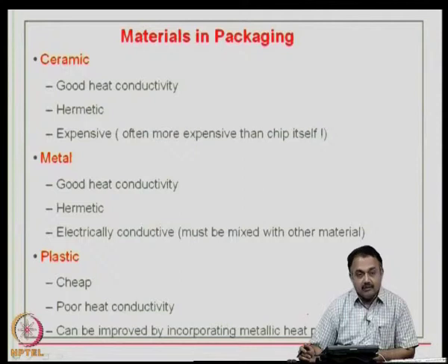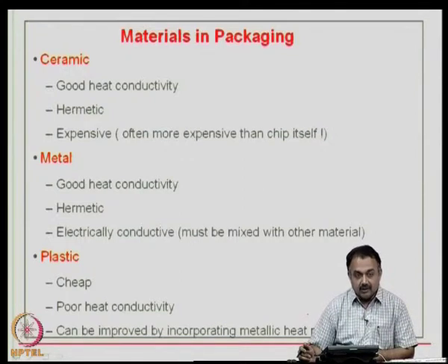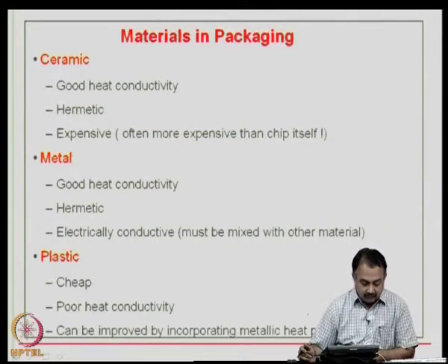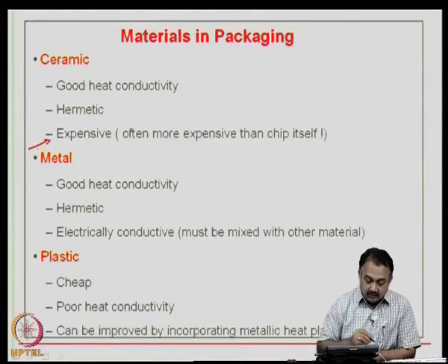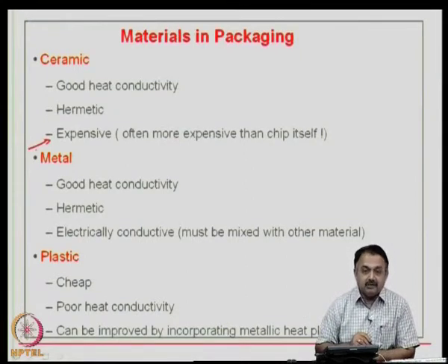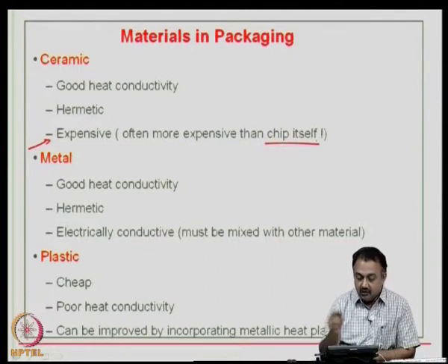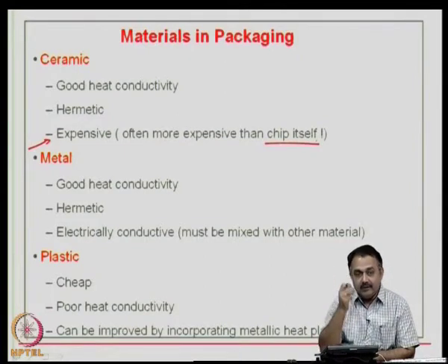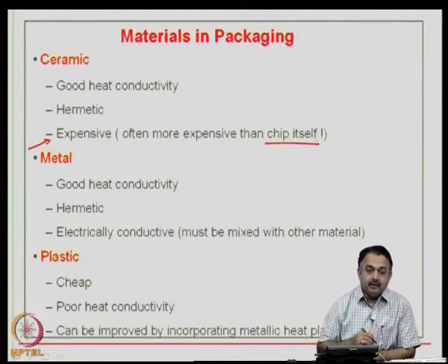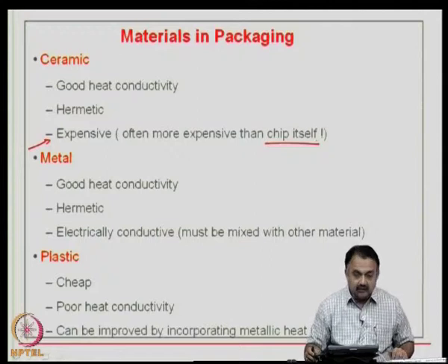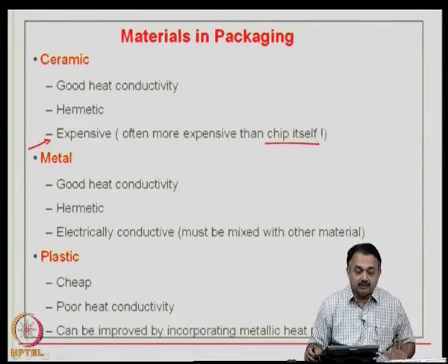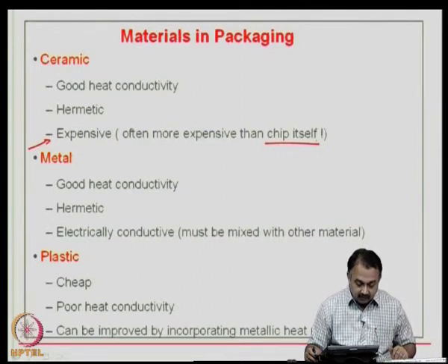So, ceramic, if you are using it, should have good thermal conductivity. It should be possible to hermetically seal the packages with ceramic. It is expensive compared to plastic packages. It is often more expensive than the chip itself. Therefore, you must be wondering, why do we need a ceramic package? But as I said, in certain areas like military, space, avionics and so on, reliability is more important because of high performance. Therefore, people go in for ceramic.